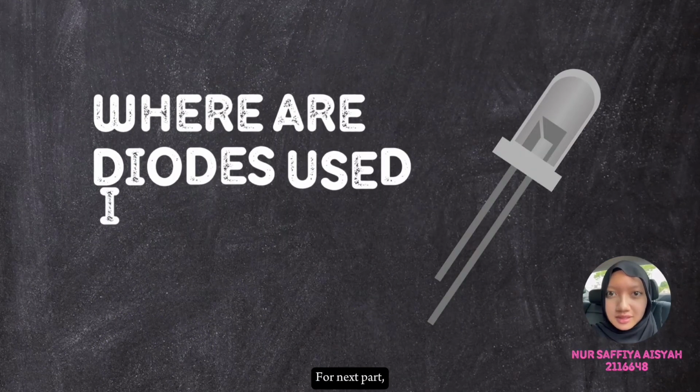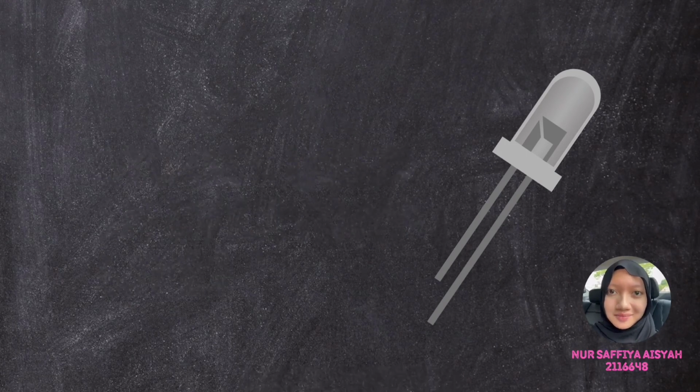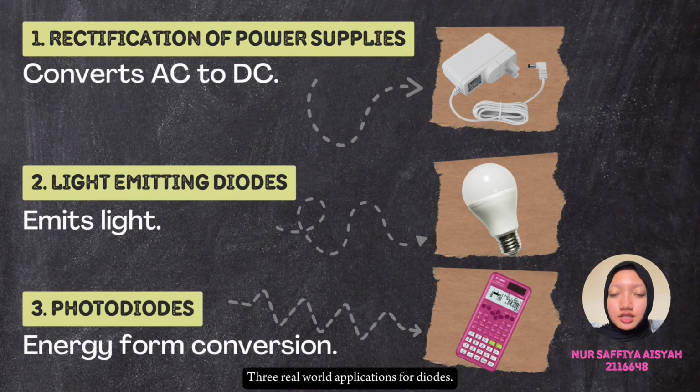For the next part, where are diodes used in everyday life? Real-world applications for diodes. Firstly, rectification in power supplies. We use diodes for converting alternating current to direct current. By allowing current to flow in only one direction, diodes help eliminate the negative half cycles of the alternating current waveform, resulting in a smoother DC output.